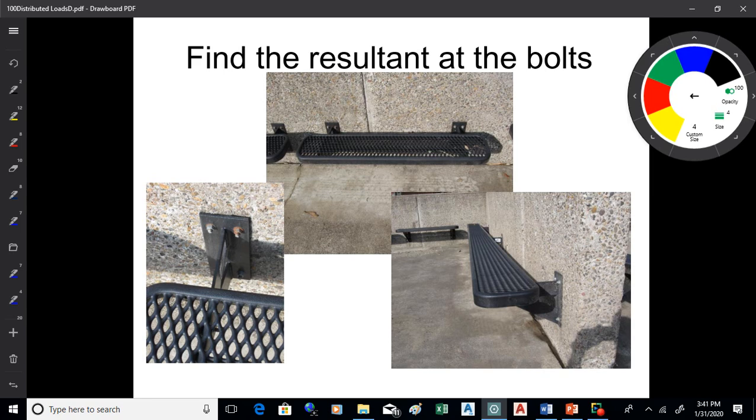Question? Do you know if something like that they would pour the concrete and then drill and set bolts, or set bolts? My guess is they drilled that because if it's a serious structural bolt, like what they hold columns up with, those are cast into the concrete. Something that small, I doubt they were messing with it. Yeah, I mean, it'd be pretty tough to get those aligned just right when someone's out there pouring concrete. Ideally, you would pour around it, but my guess is you're right. They probably just drilled it. Okay. All right. So there you go.